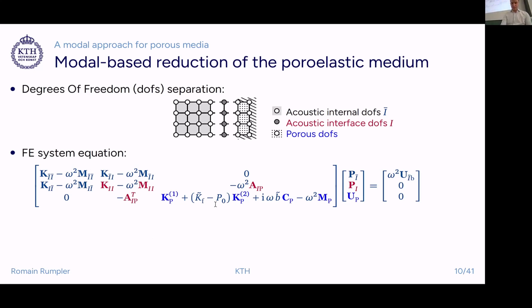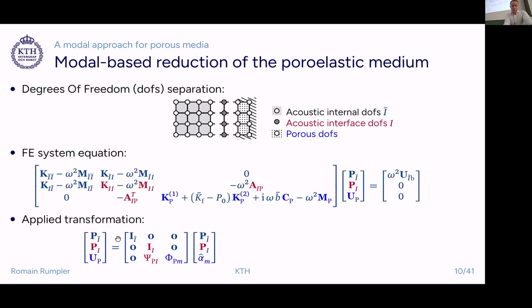So we will set up a basis just for the second part, which means that we use the traditional component mode synthesis approach, where we keep the inner degrees of freedom for the acoustic part unchanged, the interface degrees of freedom unchanged, and then we use a modal basis for reducing the porous degrees of freedom.